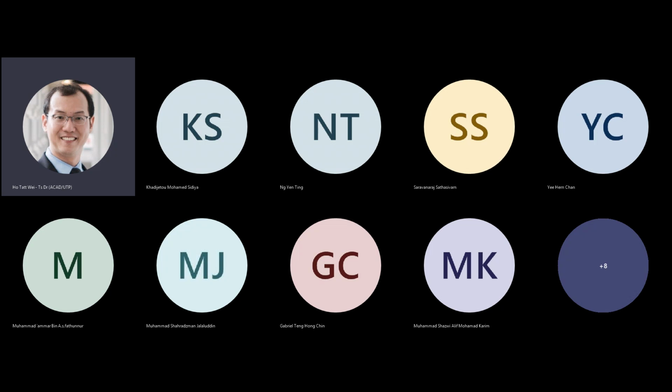This combinational logic. So we have to look at this logic from this block, from this block, from this block, from this block, from all the combinational blocks between the flip-flops. We find one path which is the longest delay. We study that path, we optimize that path. That is enough to help us to mitigate or reduce the delay of our circuit.